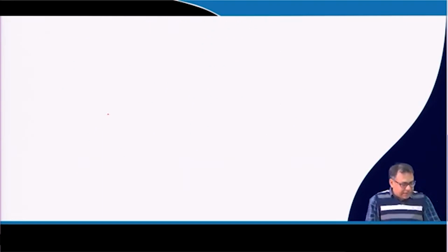Next, suppose this is the well position, and again this well is rotating about a point. So there one side will be active, one side will be passive, and I have discussed what the pressure distribution will be. If it were rotating at the base, then one side would be totally passive and the other side totally active, because in elastic theory analysis that is the case.